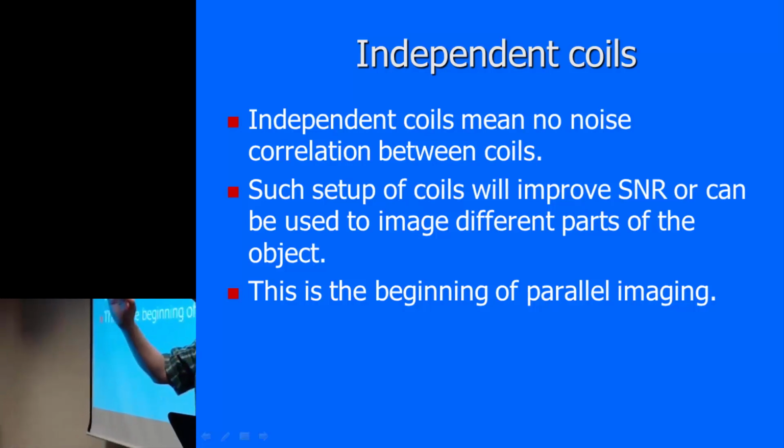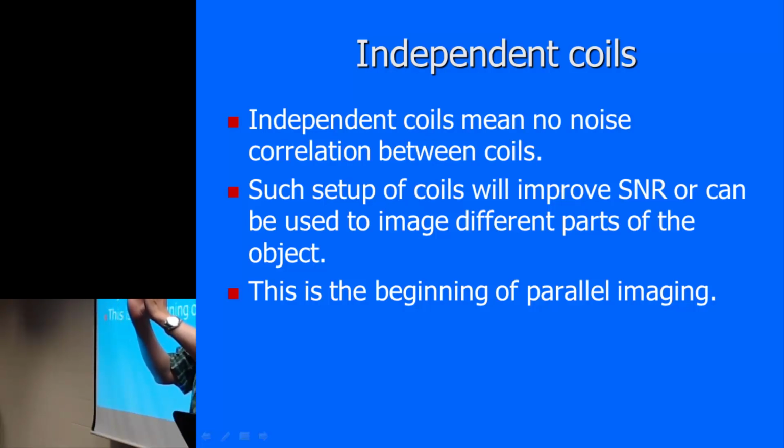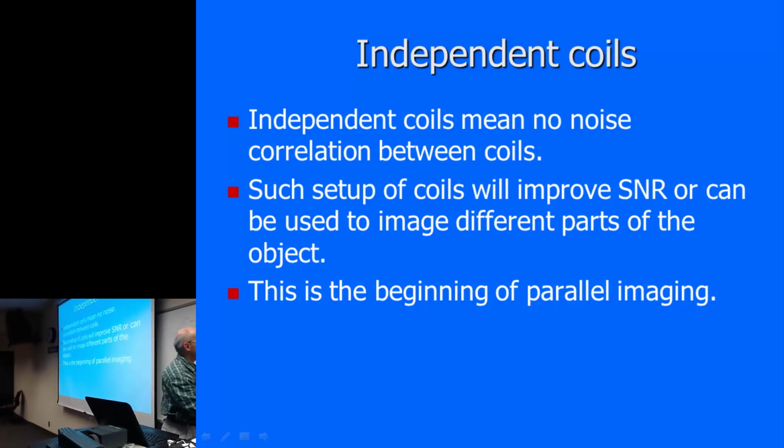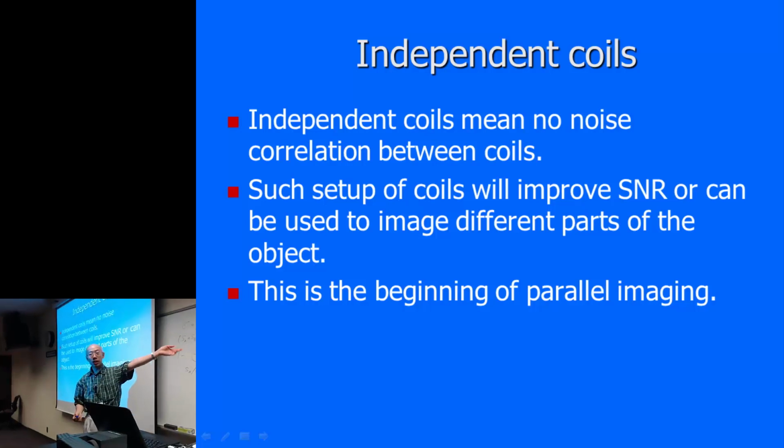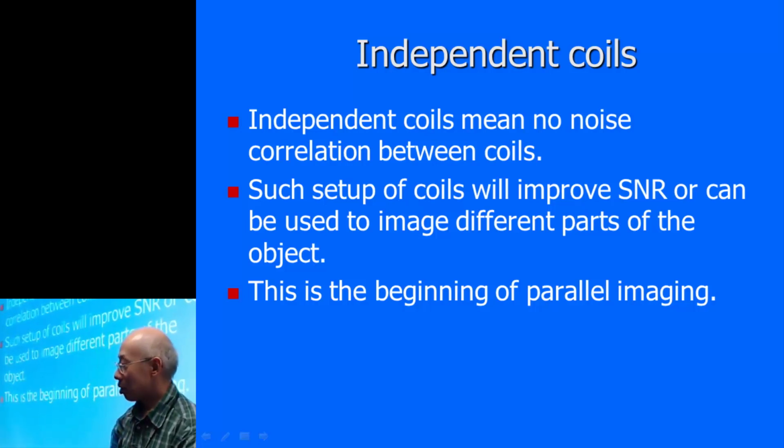One possibility is that you just overlap these two coils, but it's not an arbitrary overlapping. Let's say you have one coil here, the other coil, you overlap like that. But you have to figure out this area such that the mutual inductance through each coil is kind of 0.